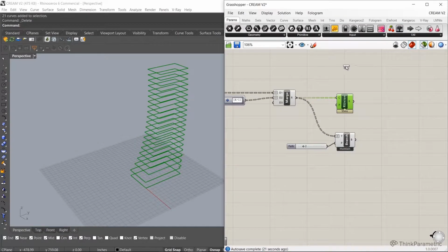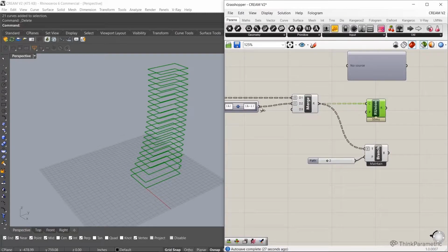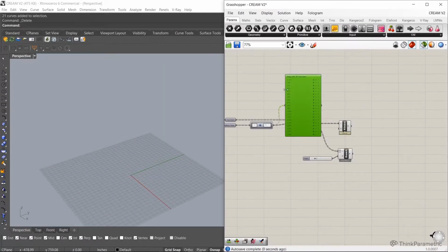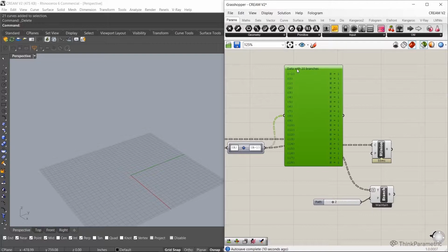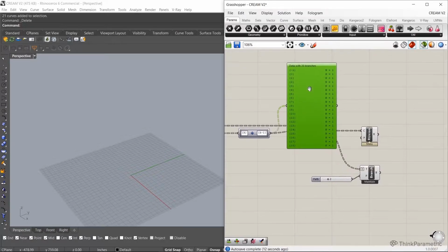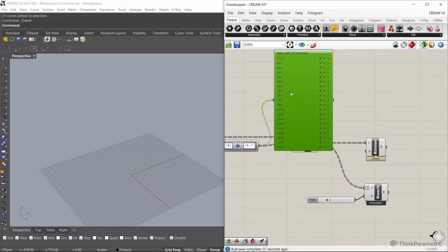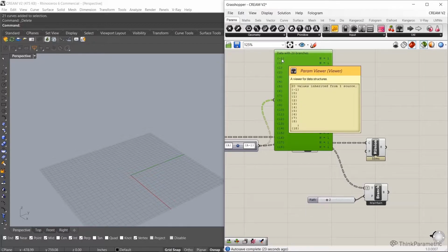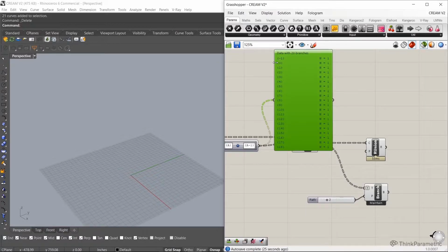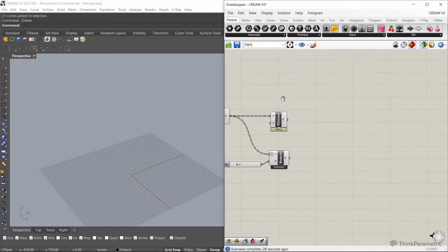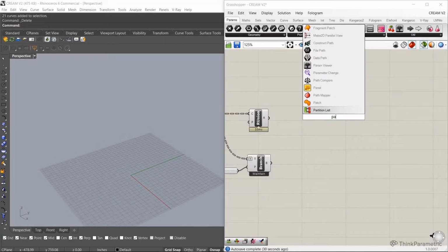What you'll notice here is when we did this, it's kind of shifted our data tree down. So now we have this kind of odd number in our data tree, this -1. I don't really want that. I want to remap this so it's 0, 1, 2, 3, 4, 5, 6, 7, 8, 9, 10, because this will eventually dictate how we name our levels, right? I don't want my ground floor to be level -1. That means my first floor will be level 0.